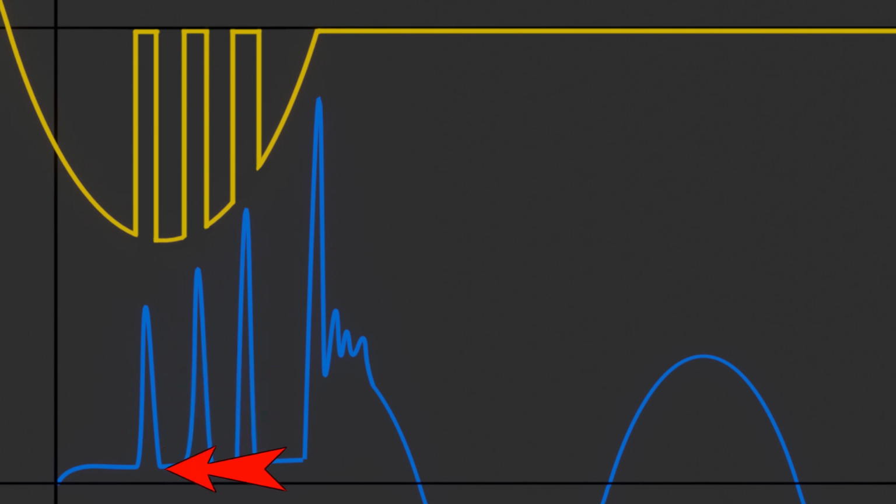This cycle continues. Even as this cycle continues, the contact gap keeps increasing because the breaker is still opening. Eventually, the distance between the moving and fixed contacts becomes so large that the dielectric medium between them becomes strong enough to prevent further restriking. As a result, the current is finally interrupted. So in this way, a very small inductive current gets interrupted by a circuit breaker that is rated for very high short-circuit current.